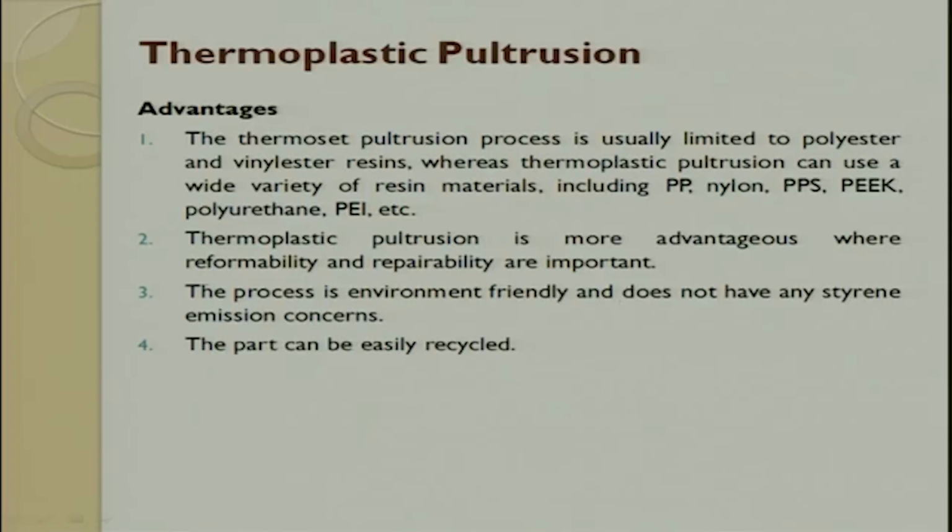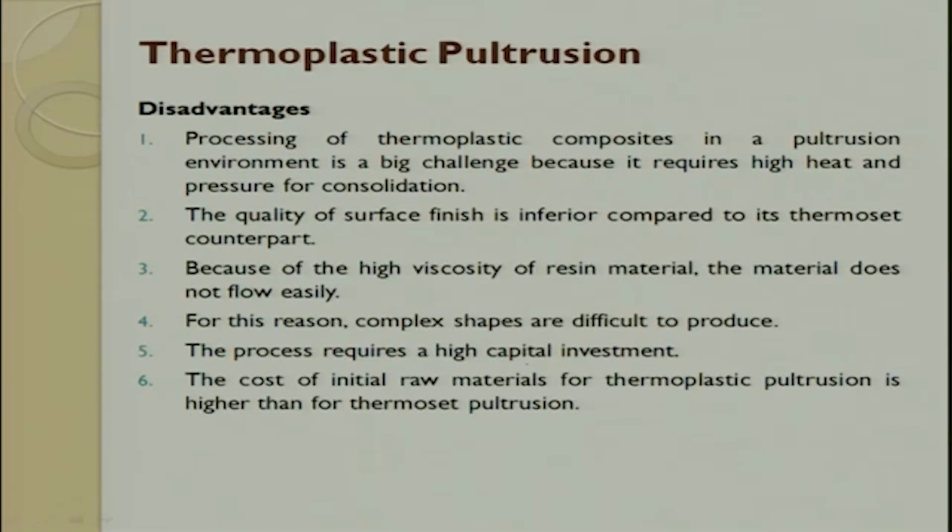So what are the advantages? Advantages are that reformability and repairability are possible as far as thermoplastic pultrusion is concerned, and the parts can be recycled. What are the disadvantages? The big challenge is it requires high heating and pressure consolidation, which puts a lot of restrictions.